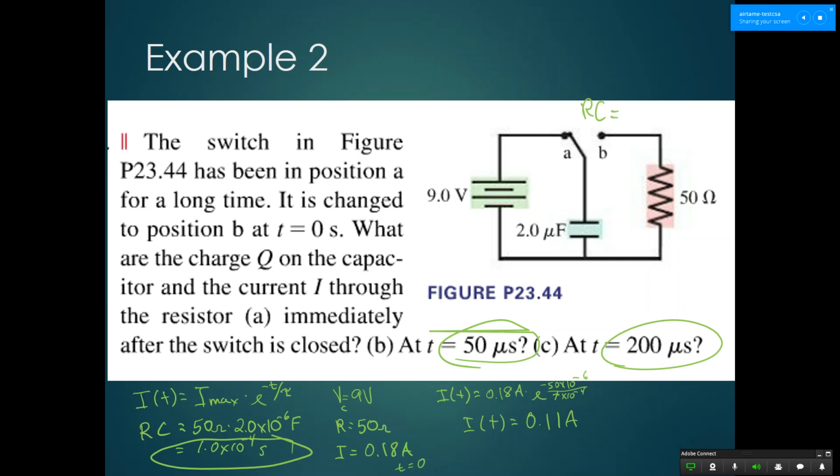So how fast is it charged? Instantaneously. In reality, your wires will have some internal resistance, so it will take some time to charge your capacitor. But theoretically, if your wires are totally free of any internal resistance, your capacitor charges like that. And you calculate it because your RC value is actually just 0 seconds.